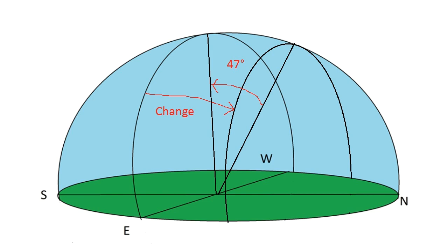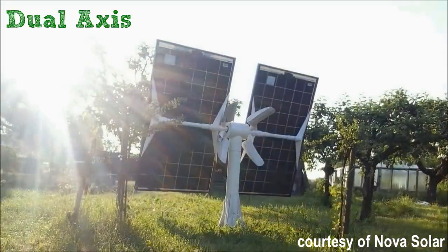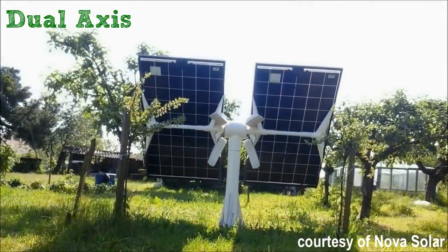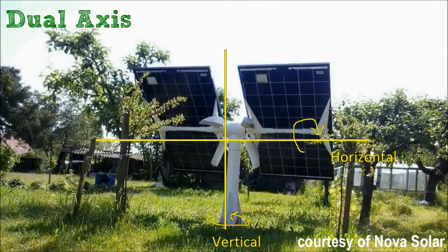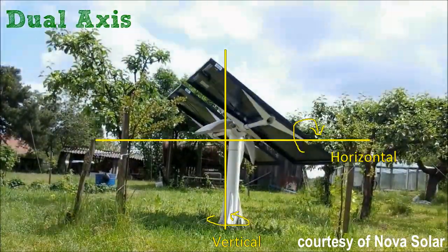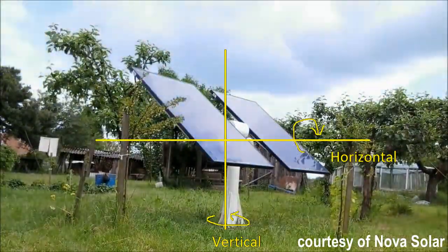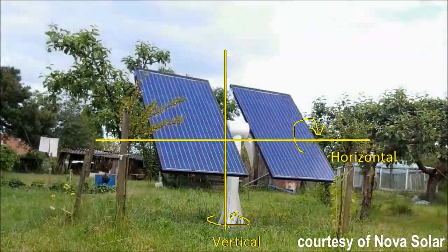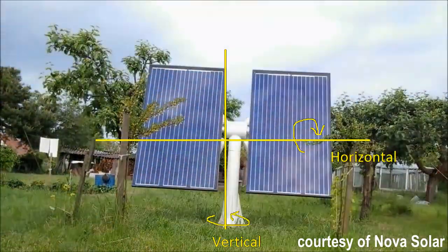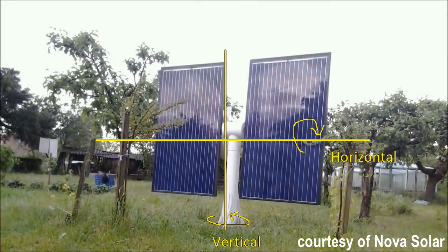Now we know how the sun moves throughout the year. So the main point of the dual axis solar tracker is to compensate for the two movements. Because it has a vertical axis, it can turn around and face east to west. And its horizontal axis is for tilting of the sun, which has a maximum of 47 degrees. Because of the two axes, it can perfectly face where the light is coming from.